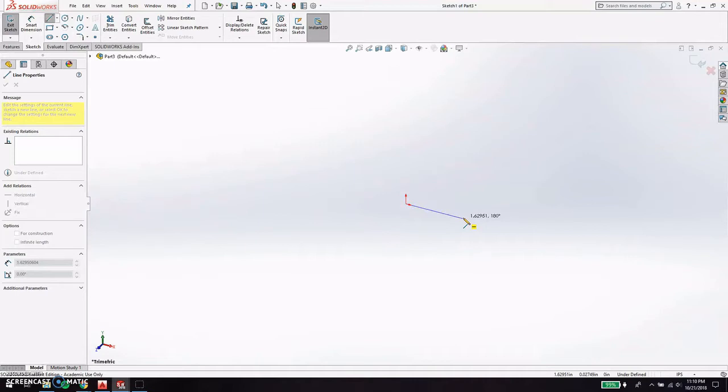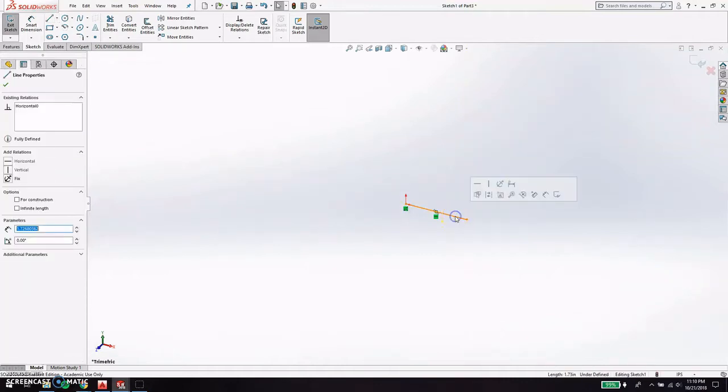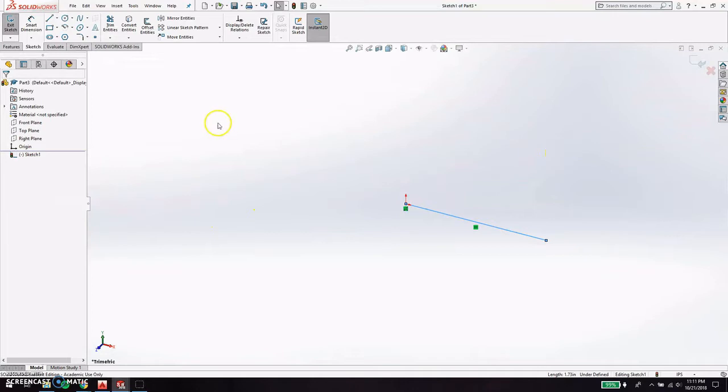Let's see. You see there's that yellow minus sign. That means that we're snapped to an easy angle, like 180 degrees. If you start going up, that thing disappears. So that's how you know that you're snapped. So let's just click, right? You see I continue drawing as if it's a polyline, so I'm going to escape from that. And then I'm going to click this, and I'm going to make sure that it's the right dimension, same way that we've done before. So I'm going to click 4 inches, and that's great.